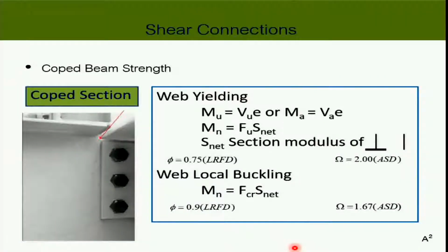Okay. Another issue that we may need to consider is the coping of the beam, because in real construction we need to sometimes keep the level of the beam at the same height, so that we can install the floor on top of it. So that means for some details, in order for it to work, you need to cope the top half of the beam out, so that the beam can be installed into the primary beam like that. So this is supposedly the secondary one, right?